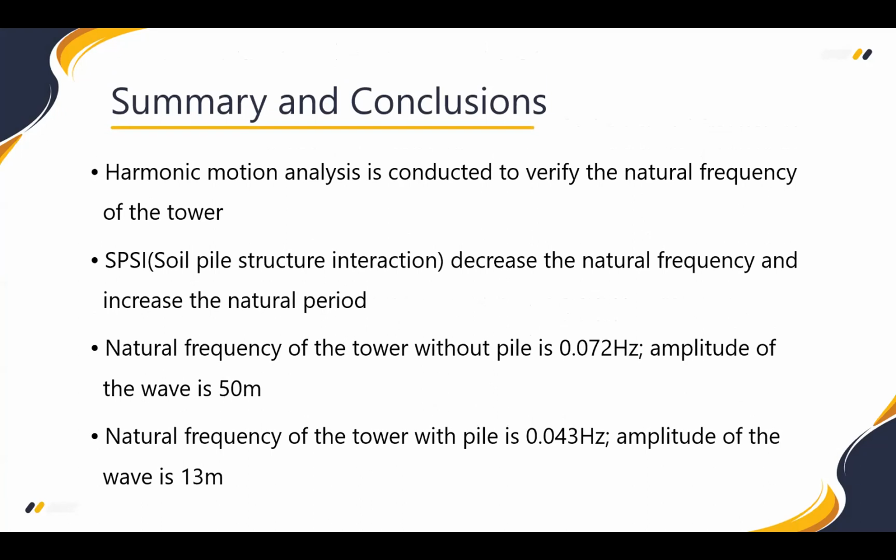What our group basically did is conduct a harmonic motion analysis to verify the natural frequency of the tower. The result manifests that SPSI, which means soil pile structure interaction, will decrease the natural frequency and increase the natural period of the tower. It also means that with SPSI, the piles are really helpful in resisting vibrations caused by earthquakes and increase the stability of the tower.